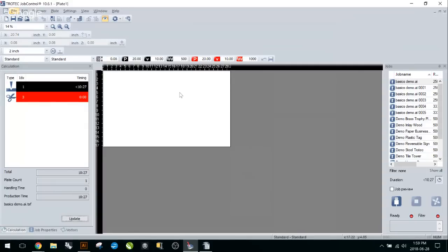Just make sure that all of your colors must be RGB colors. That's one of the biggest things you have to remember. So make sure that your document color mode is set to RGB, and the colors in that document are also set to RGB colors. Use a stroke weight of 0.001 to make any cuts. If they're not 0.001, your laser will not register your cut lines.